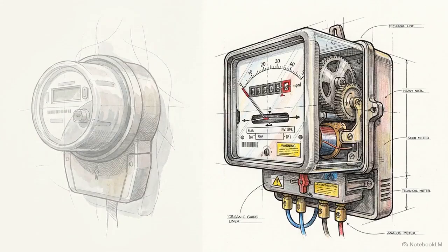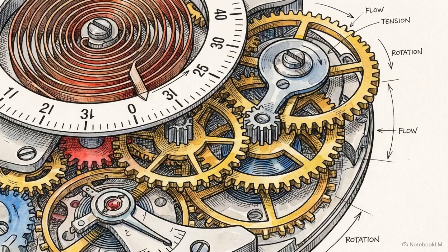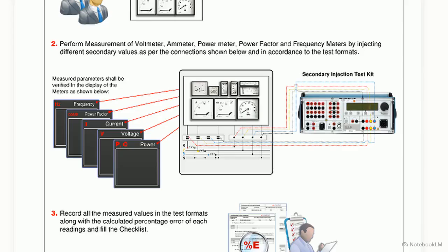Procedure 14.2 shifts focus to legacy analog and digital meters. Here, the primary objective changes. Instead of validating a network data link, you are validating a physical mechanical scale. The initial setup requires precise physical verification. Before you energize any test leads, you must verify mechanical 0. You confirm that the analog needle rests on the 0 mark without any voltage applied.